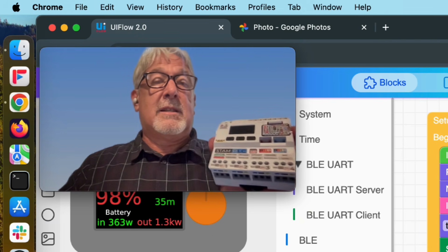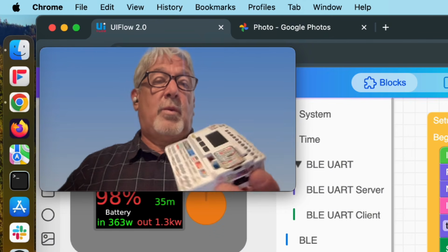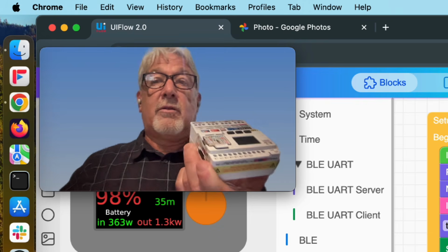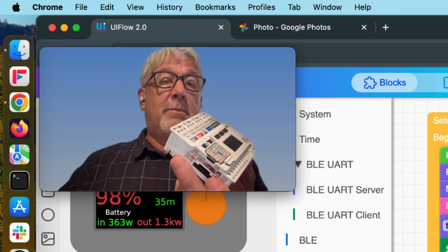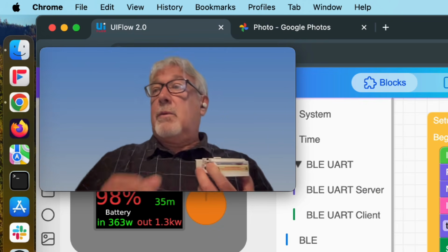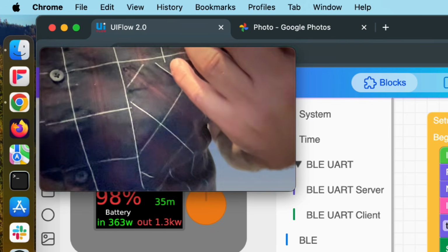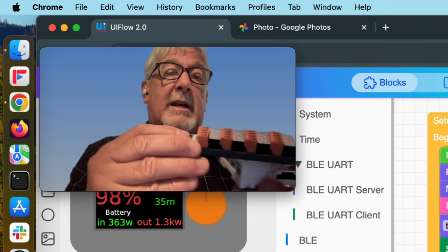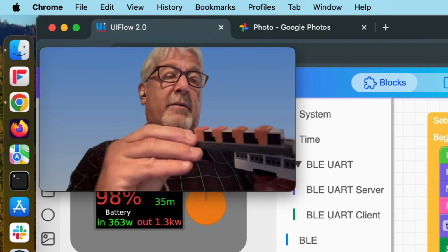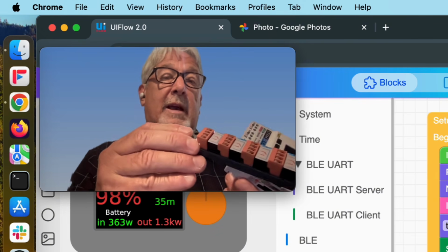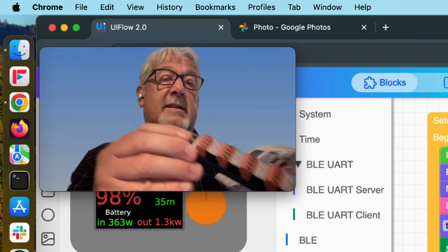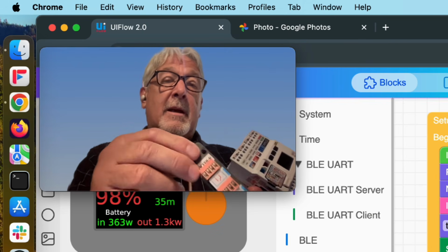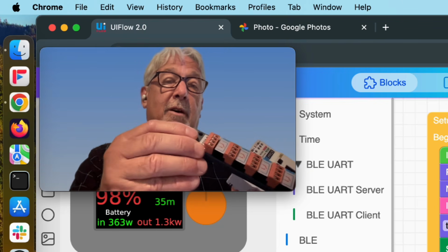and this is industrial quality, fairly robust, and one of these can control multiple circuits, and then I can plug extenders into this. So if I plugged in this, that adds 4 more 10 amp relays, so the 4 on it and the 4, so I can control 8 circuits altogether. I've got 8 digital inputs, so I could monitor the switches to see if they're on, see if they're off.